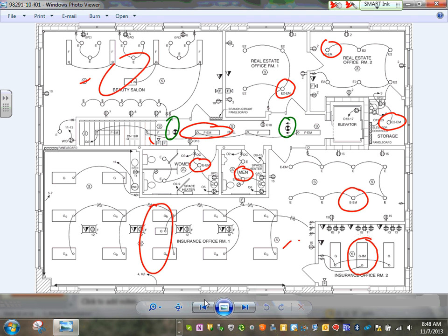What are the requirements for where those are supposed to go? Good point. The emergency lights are supposed to light the egress path. The egress path, guys, will be decided by the architects. For example, if this is an office, here's the exit of this room. Only one door, because that's a closet, so you don't need an exit sign.